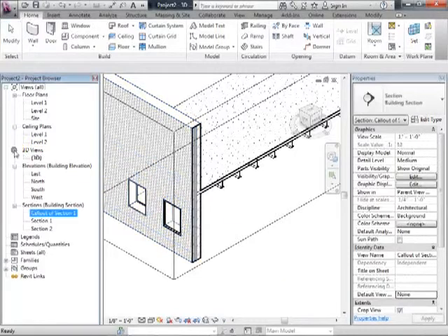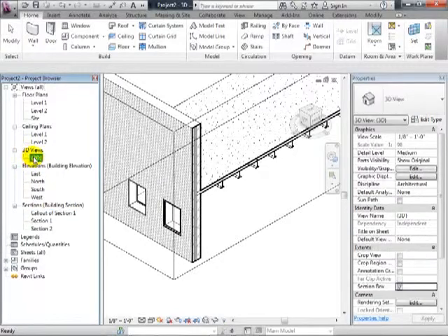Okay, do this as your final thing for today. Go ahead and open up the project browser. You have that default 3D view. It looks like 3D, so go ahead and choose that. I want you to right click on that, and we're going to say duplicate that view.